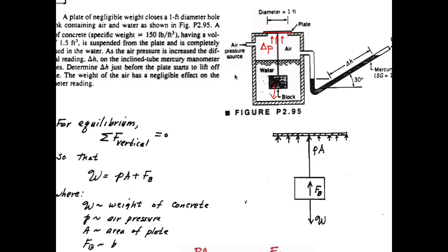And I suppose the interesting thing to realize about this is that if you look at, for instance, this weight, we know that if we draw the fluid pressure and how that fluid pressure changes with depth, then the whole idea of buoyancy is that if the pressure here is atmospheric and this is the fluid pressure distribution, then the mismatch in fluid pressure between the top and the bottom, which probably shouldn't use delta P here, let's not use delta P, they just use P. The difference in pressure between the top and the bottom is equal to some amount given just by the height of this, and the gradient.